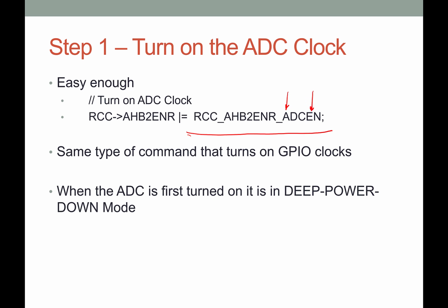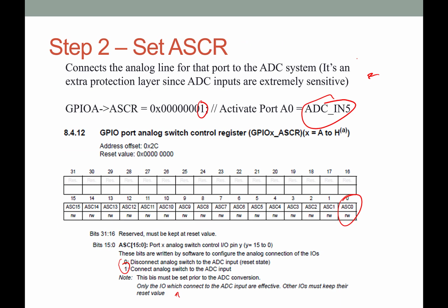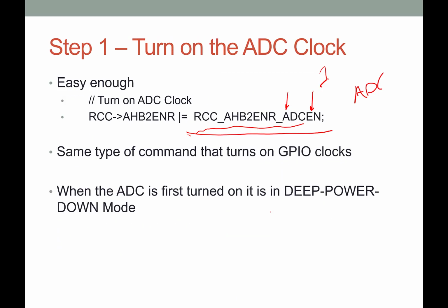It looks confusing, but it is in that startup file, and if you look under the analog to digital conversion section of that startup file, you're going to see that this ADCEN sets a bit, just like anything else. It's like setting bits in this register, but it's setting a bit that basically says, okay, start the clock. This is the same type there.